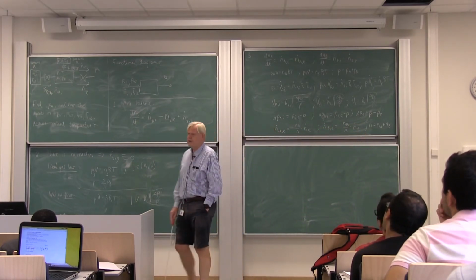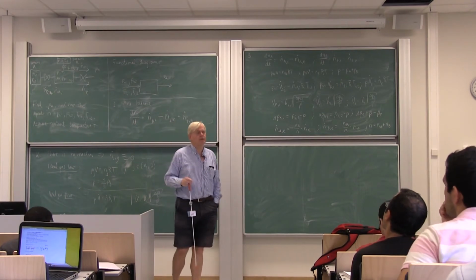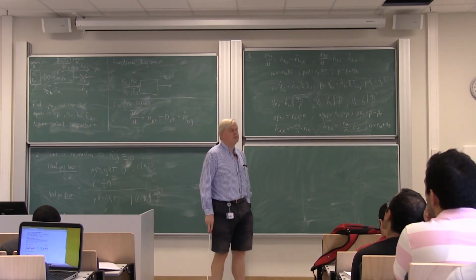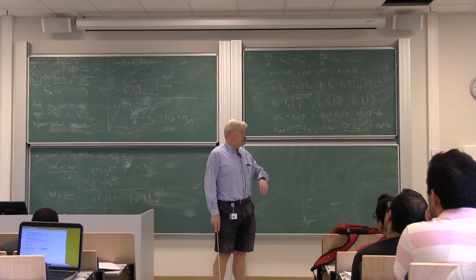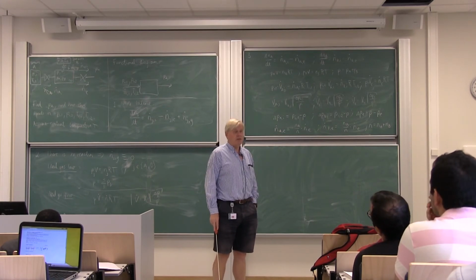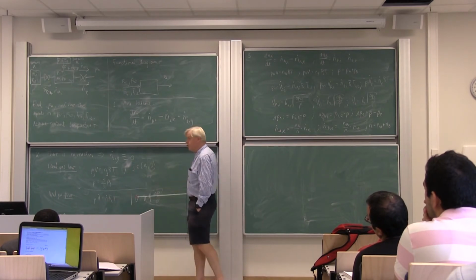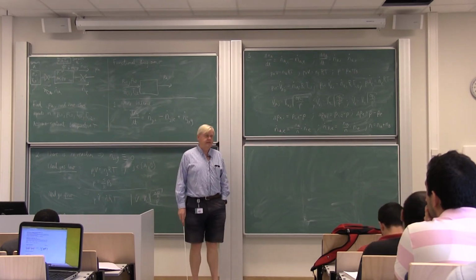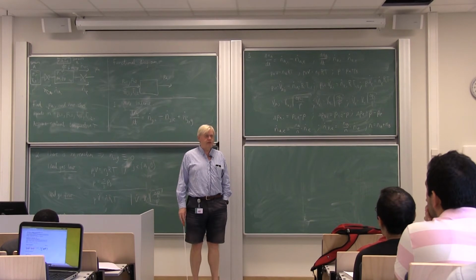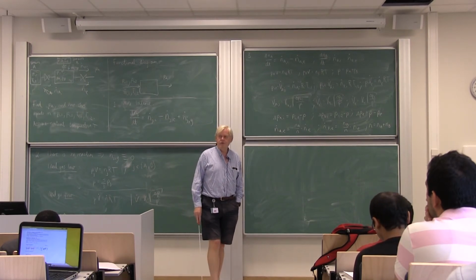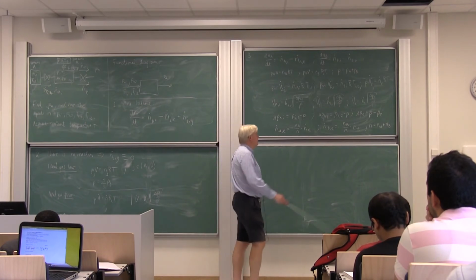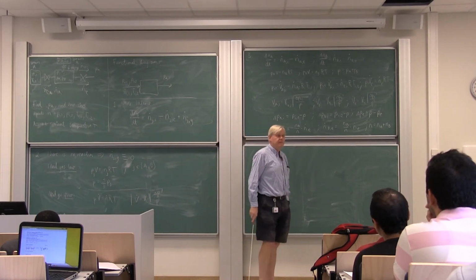Suppose now that we have spent a lot of energy on converting it to ODEs, and then we suddenly decide, oh well, maybe we want a different expression for the flow rate. Then we have to redo it. But if we use the DAE formulation in Modelica, for example, we just have to change one equation maybe.